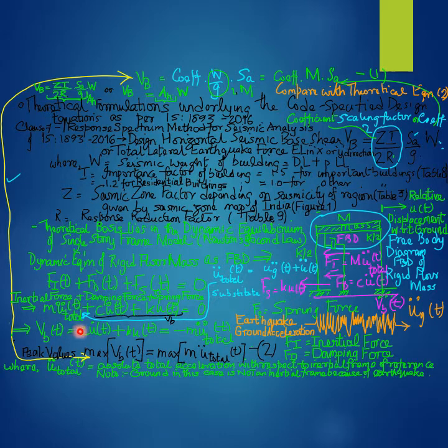So recognizing the sum of the latter two terms, the second and third terms, corresponding to the dynamic damping force and the dynamic spring force in the dynamic equilibrium equation, constitute the theoretical dynamic base shear, also a function of time or a time variant function.